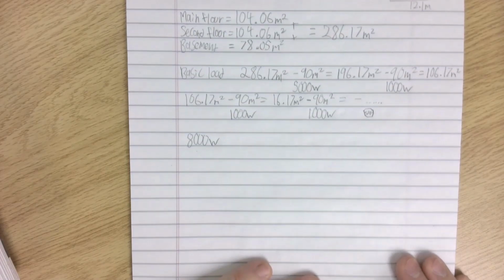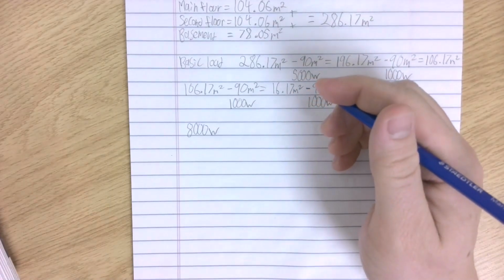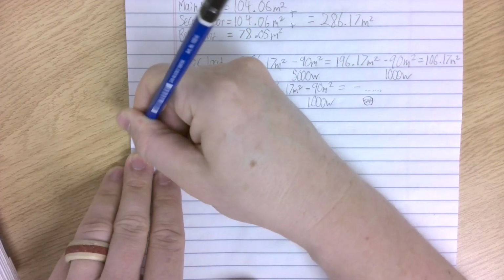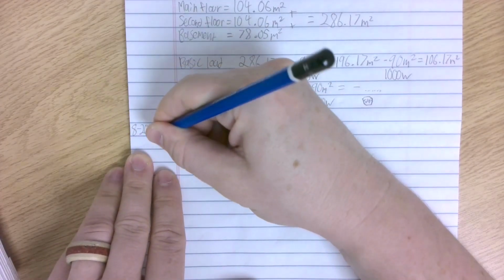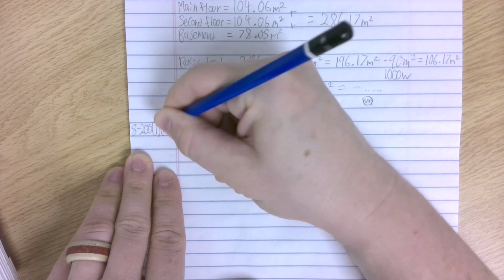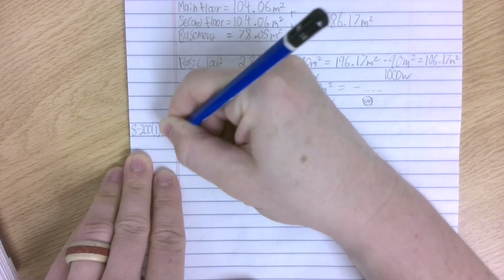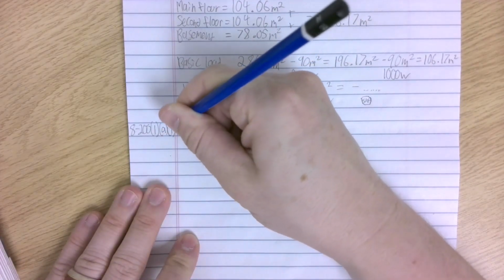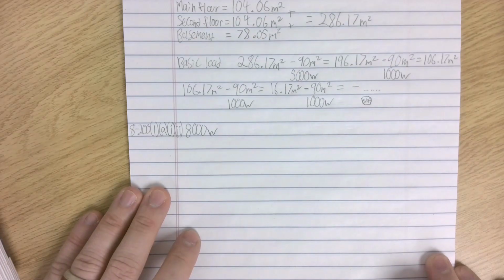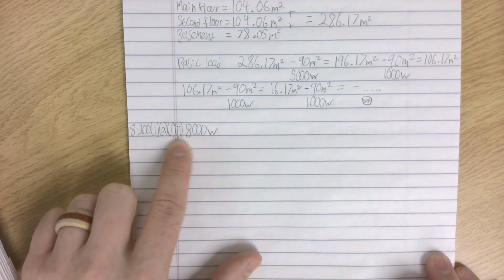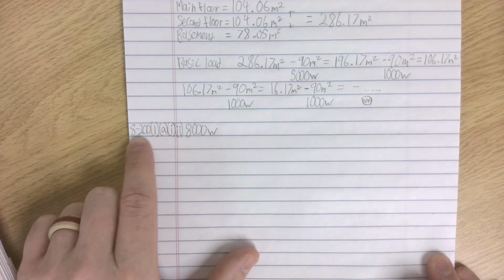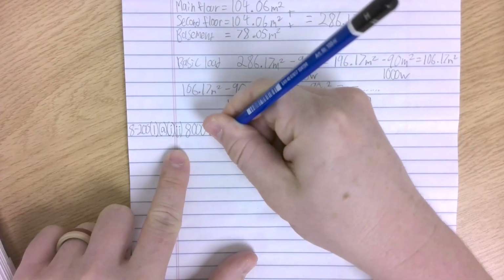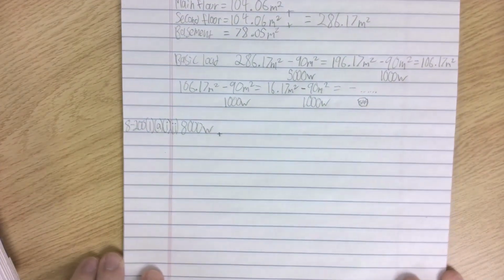And now for the overall calculation, I'm going to start to organize to make sure I don't miss anything. I'm going to organize it like this. So I'm doing rule 8200, 1, A, I, and it's actually also II, or 2. That's because I know what this subrule and item is talking about. I know that's my basic demand, and that's the first thing I'm going to figure out for this service calculation for a house to add up.